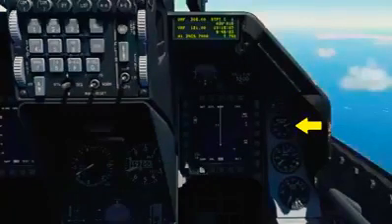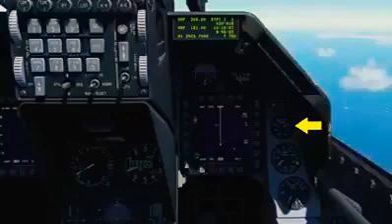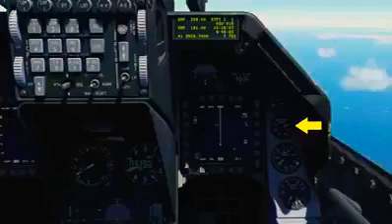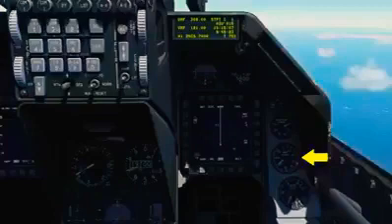The engine nozzle is variable and consists of two sections. The divergent nozzle moves freely in conjunction with the convergent nozzle. The convergent nozzle is actuated by 4 hydraulic actuators, and the percentage of the nozzle opened is indicated by this gauge. The RPM indicator indicates engine RPM, supplied by the engine alternator, and it's expressed as a percentage value